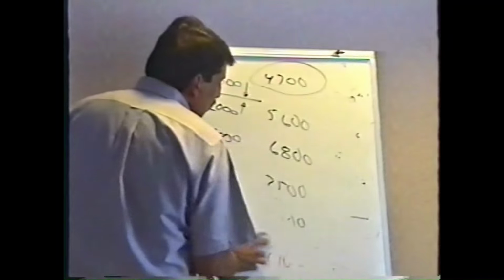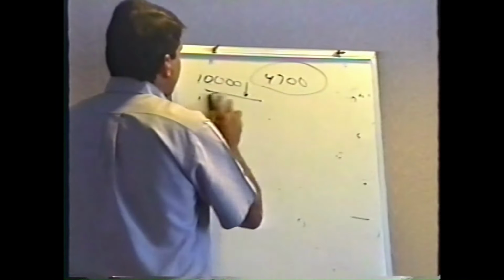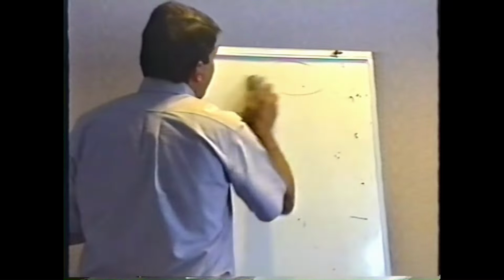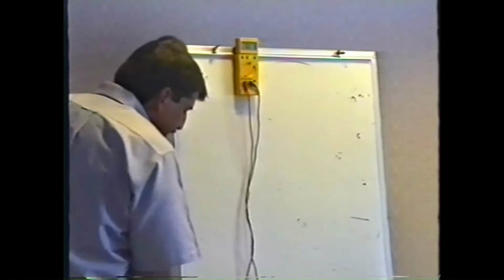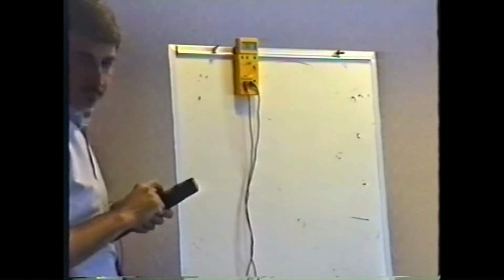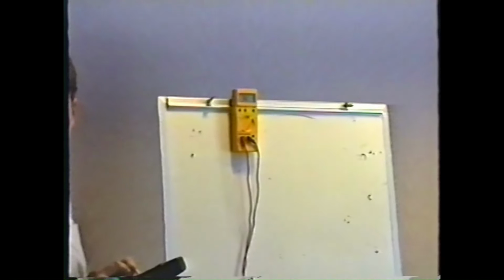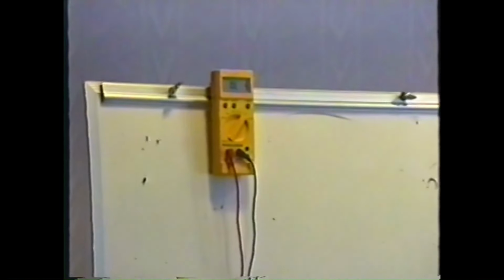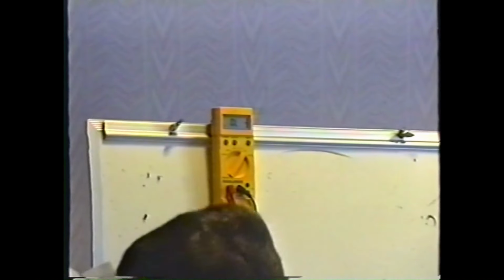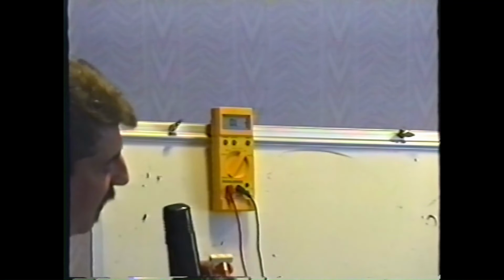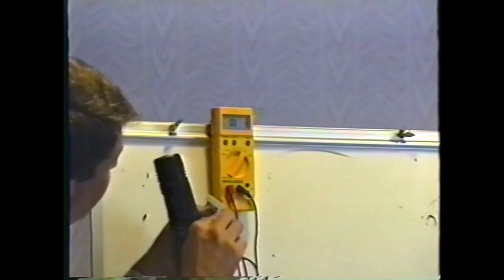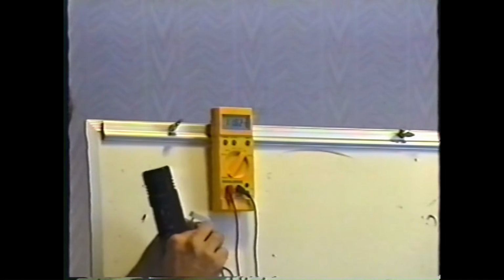Now, when you have a bad resistor, what you'll measure is an open circuit. I put my meter on ohms. I have a resistor here that is supposed to be 2 ohms. It says 2 ohms on it. So you would expect it to be almost like a short circuit, basically. It's only 2 ohms of resistance. When I put my meter leads across the resistor, you see the meter does nothing. It does nothing at all.